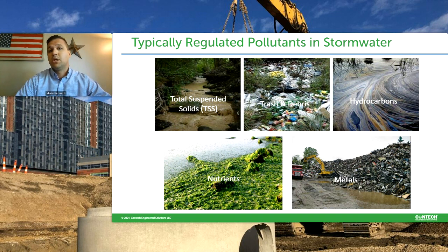But there's also the need in certain stormwater applications for nutrient and metals removal. If you've worked with Contech in the past, you may have seen Contech storm filter or Filterra for that. But for hydrodynamic separators in particular, any removal of those 2 would really be incremental, as it would be coming from the particulate bound matter there. With that, we don't really quantify any removal around those 2 components.